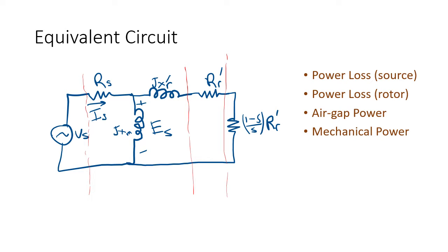Okay, so here's the equivalent circuit. To just quickly go over through it, we have the source power, and this is a per phase model. So in other words, for each of those colored wires, they're going to come within this one. So this is the source, the power that you can supply it with. It's going to have to be AC with the given frequency.